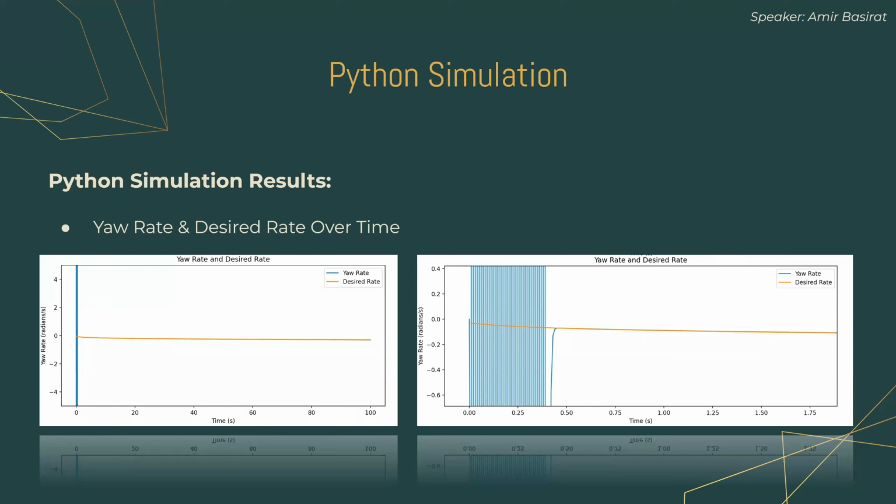So the second graph shows how the yaw rate and the desired yaw rate change over time. The closer these two values are, the better our system is performing. As shown in the graph, our system effectively managed to keep the actual yaw rate very close to the desired yaw rate. Which means our torque vectoring system is performing as planned to improve the car's control and movement.